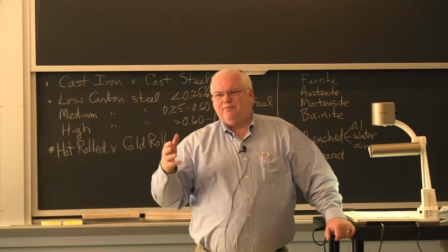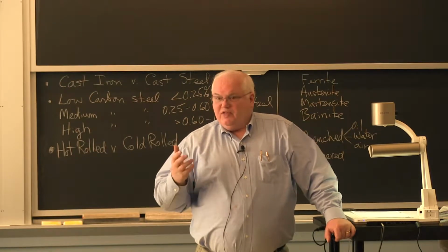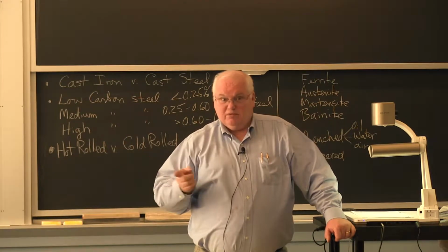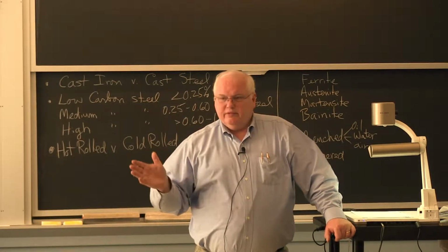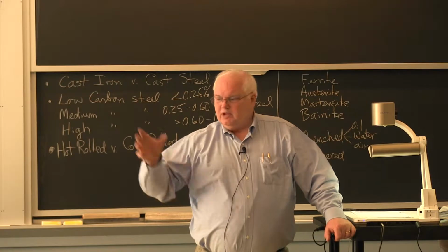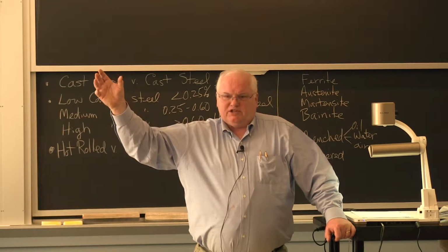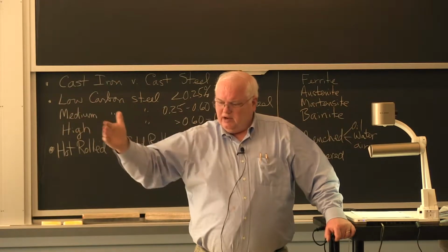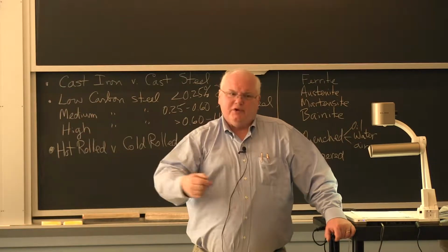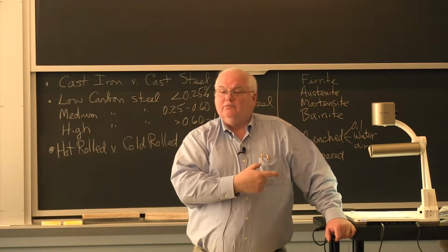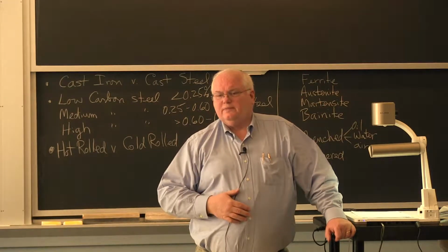Okay, B-A-N-D. You take the hot rolled band and you take it over to another mill, which might be a $1.5 billion proposition today, which is called a cold rolling mill. And now you're basically going to put it through at room temperature through these big, massive rolls, and it'll be going through there at 60 miles an hour. And there'll be not just one set of rolls, great big rolls. There'll be about 6 or 7 rolls lined up, one after the other, so it comes in at 1/4 inch, and it might come out at 25 thousandths or 30 thousandths.